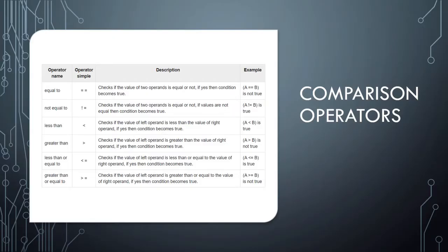And so in these commands, we talked about having a condition, right? So we're saying if the push button is on. Well, how do we say that? We can't just write those words in the code and say if the push button is on. What we would do is we would say if the button state is equal to low, right? Because low is the condition that the button is being pressed in. And so we would use these two equal signs up here as part of our logic. And you can see this example over here.